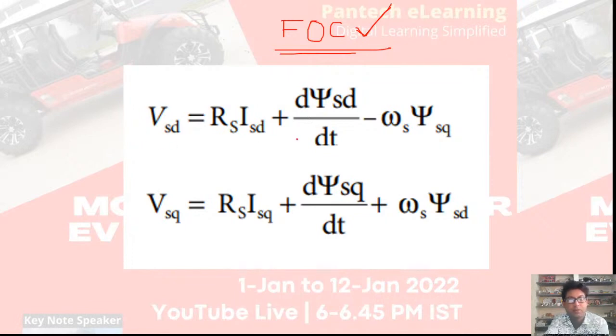so these two equations are the stator voltage equations. Yesterday I told you, this is the stator direct axis equation, which is nothing but stator resistance into stator direct axis current plus rate of change of stator direct axis flux minus synchronous speed into stator quadrature axis flux. Similarly, stator quadrature axis voltage is equal to stator resistance into quadrature axis current plus rate of change of stator quadrature axis flux plus synchronous speed into stator direct axis flux. Okay,